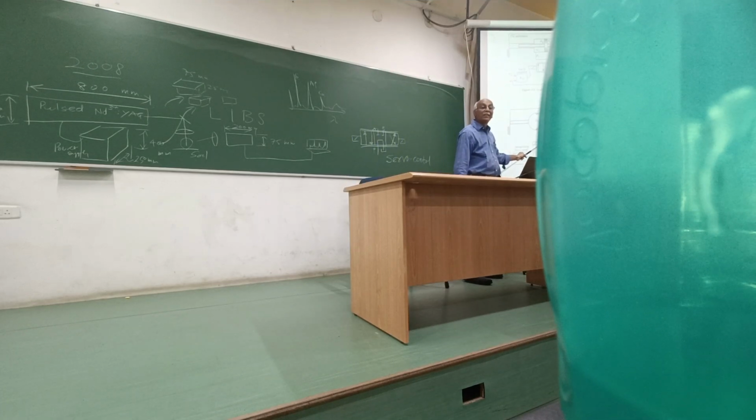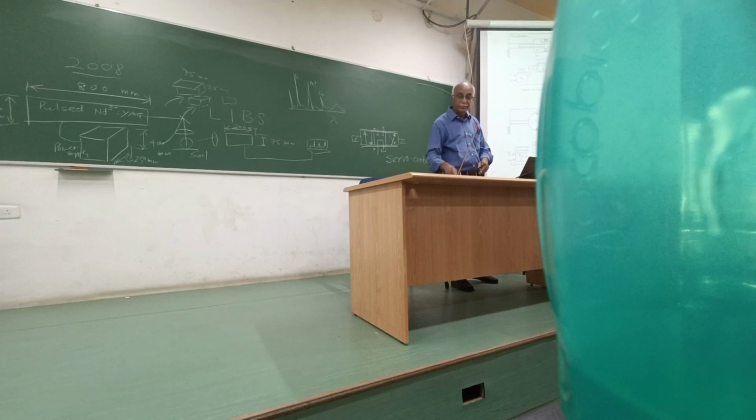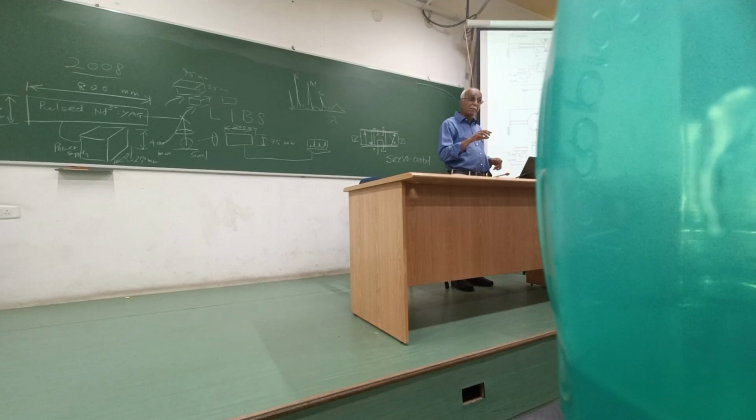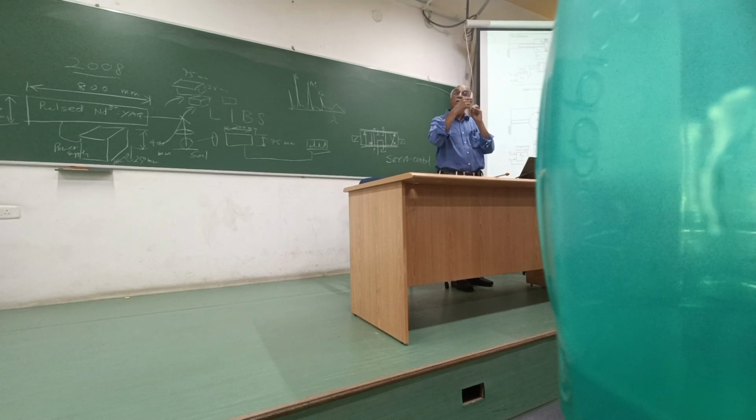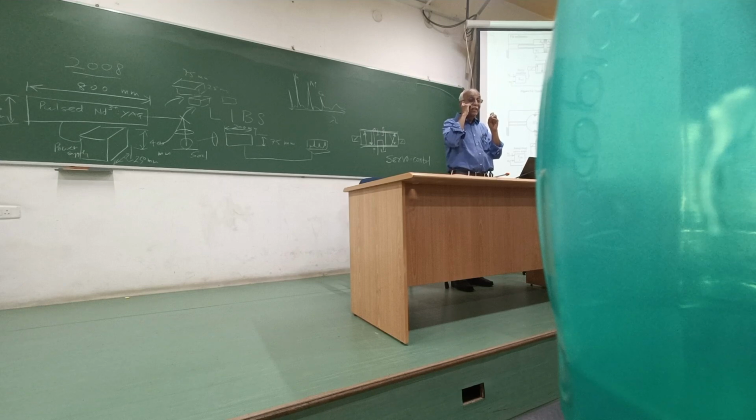It can be speed sensing using either a small electric motor type or generator type, or it may be based on rotation, or based on an optical system coupled with encoders. Encoders will help us pick up the speed of rotation.